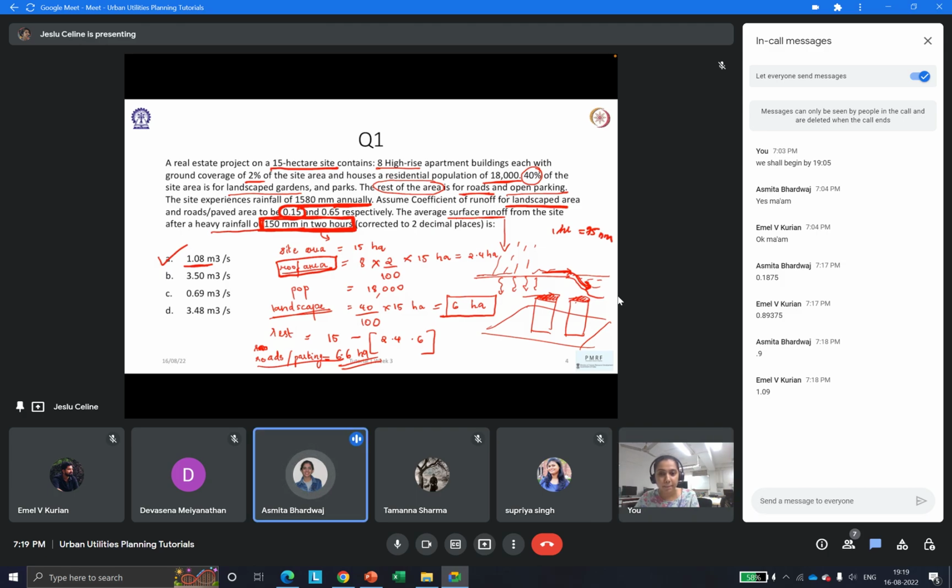Basically, the rainwater which is collected from the roof, it goes as groundwater recharge through pipes. Very good. It does not act as a surface runoff. Very good. Exactly. That's the answer. So whatever is connected from the roof does not act as a surface runoff. So this is a very important point because usually this is where the calculations go wrong, because we might assume that whatever is there in the terrace or the roof, we capture that and that is also put down. No, but it's usually drained through pipes. So that is good. So I think this question is clear right now.